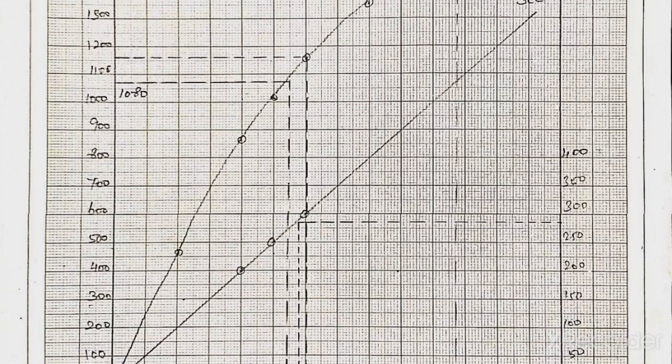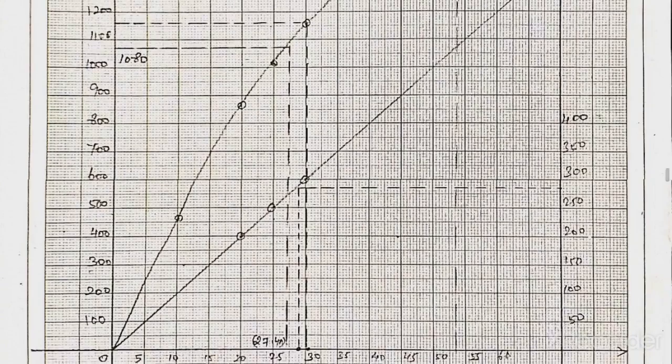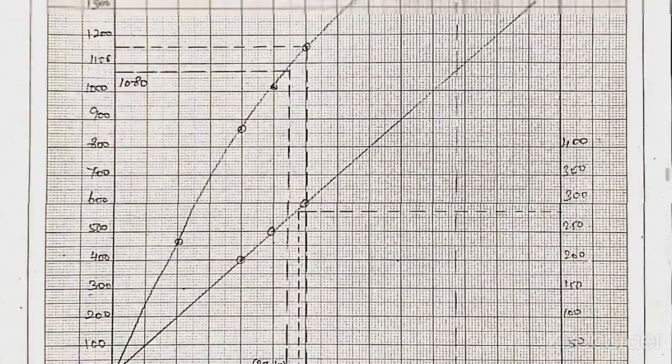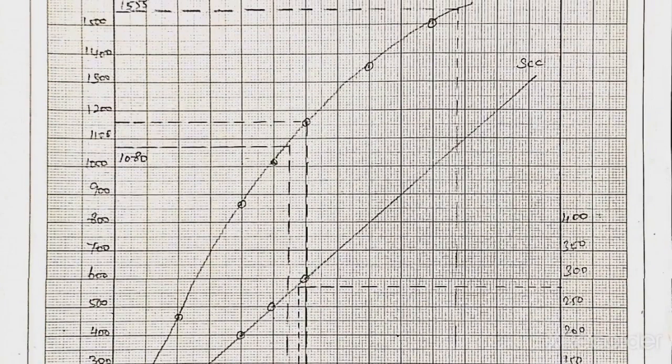Where we need the value of voltage, we directly hit the OCC. Once you know the current, you go and hit the SCC curve. Where the voltage or induced EMF is to be determined, there the field current will hit the OCC curve and we find the voltage value. So 27.4 will hit the OCC curve. We find the induced voltage E0 is equal to